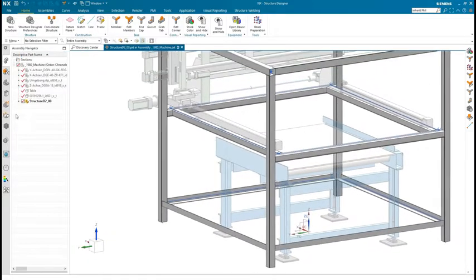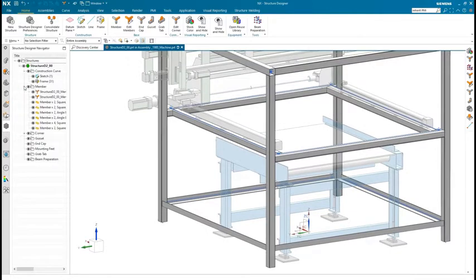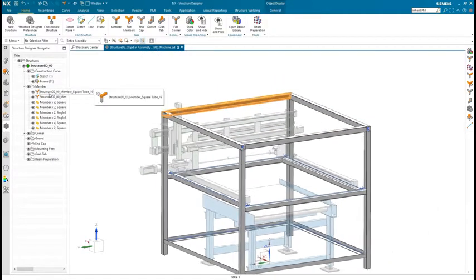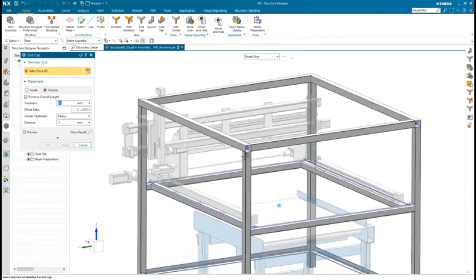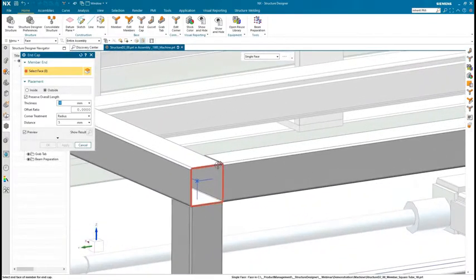As we select members in the Navigator, notice how they are packed if they are geometrically identical. Should a packed member be modified with the addition of, say, a mounting hole, it will be automatically removed from the collection. A similar packing process can be used to consolidate members to create drawing cut lists.